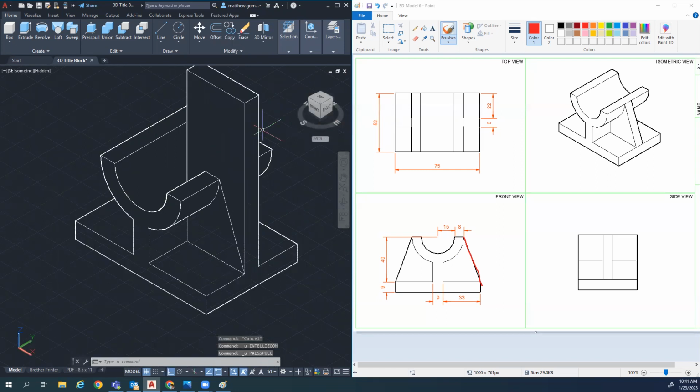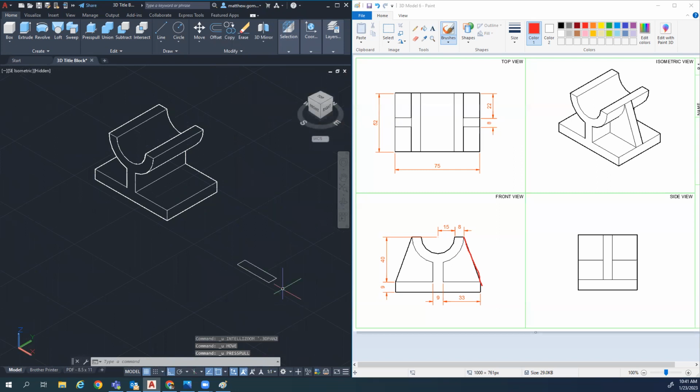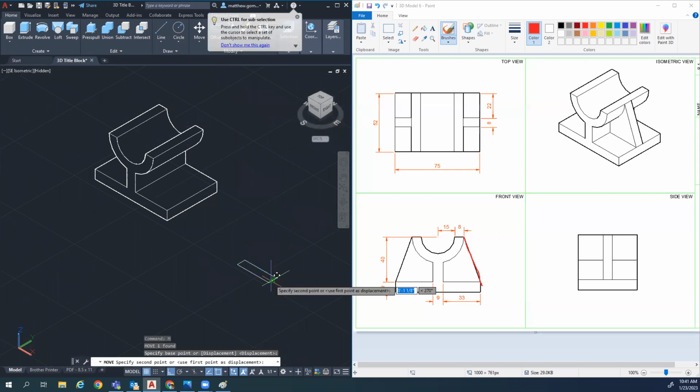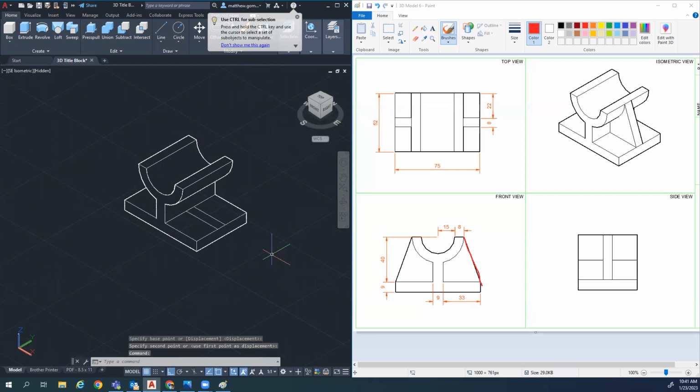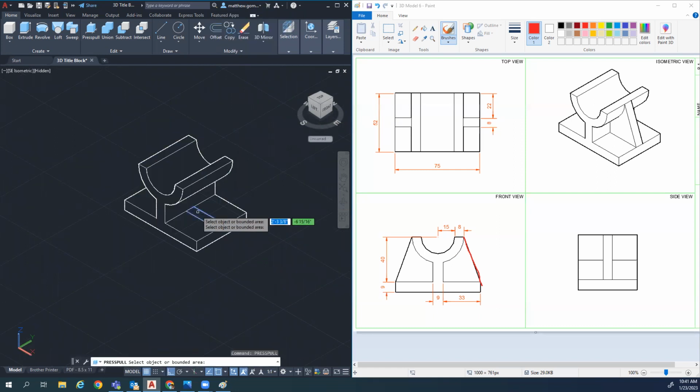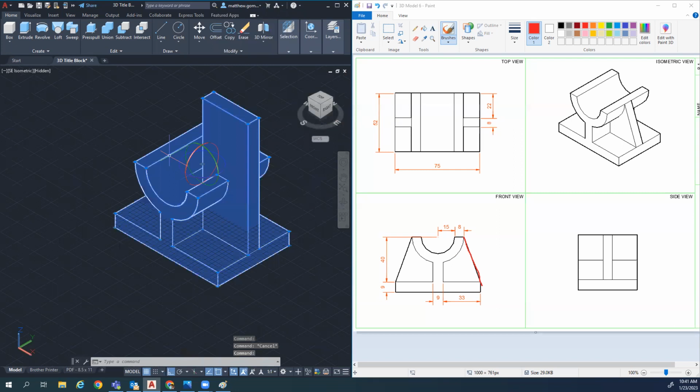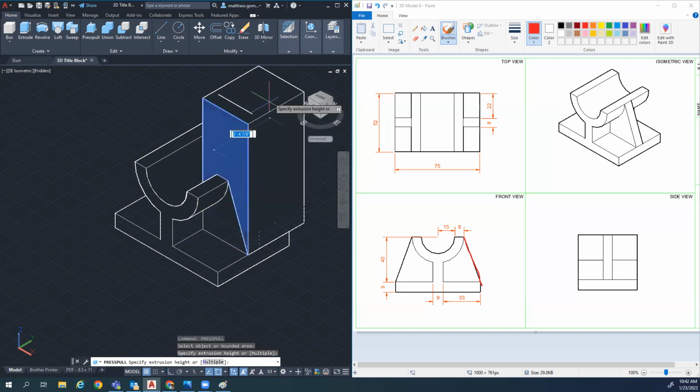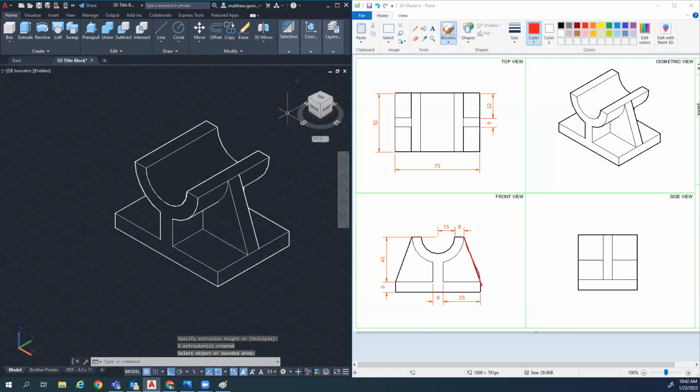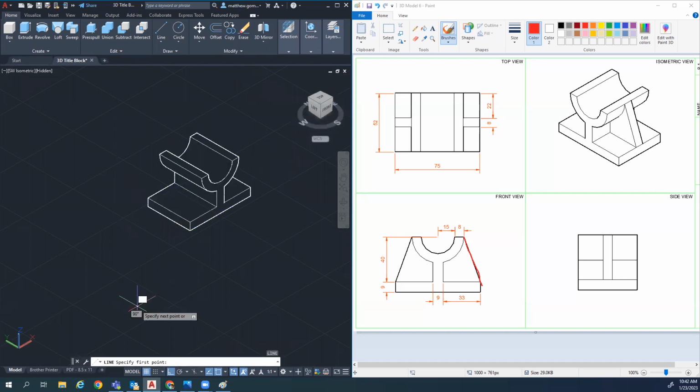The easiest way to do it is once you draw your box, join it together and then move it to the point before you press pull it up. Because when you press pull an object up like this, that's already connected to the object, it automatically unions them together for you. It's already a connected part. Then you can skip the whole union part and draw a line from quadrant to there and press pull this back to there. Okay, so 2 ways to do it. Same thing happens on the other side. I'll do it the correct way first this time. It's just making a box oriented the correct orientation. That's 33 by 8.